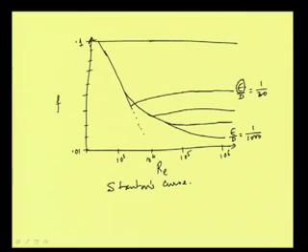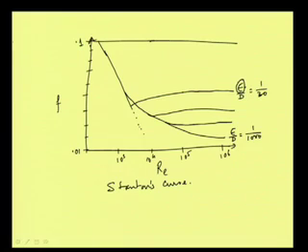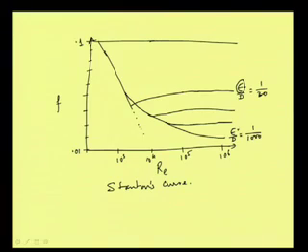Again, Moody conducted different experimentation on this issue, and he also gave his own sets of curves. Then he provided a table for this roughness value for different materials. If the material is wood, if the material is steel, if the material is concrete, then for different types of material, what will be this roughness value. That was also given, and then it became convenient to use this relation. So, knowing the material, we can take a value of roughness.